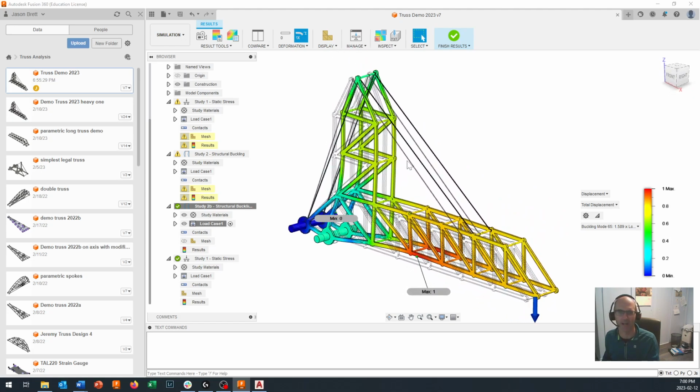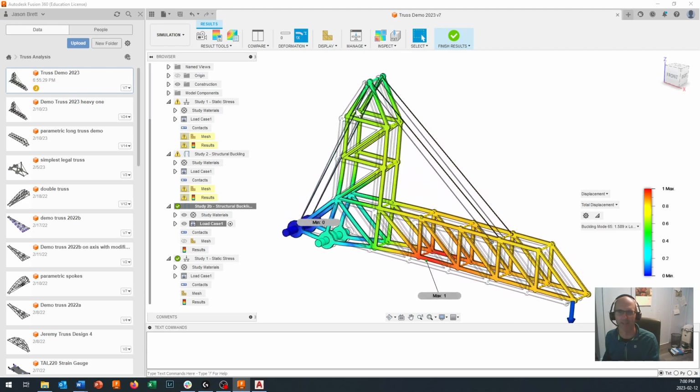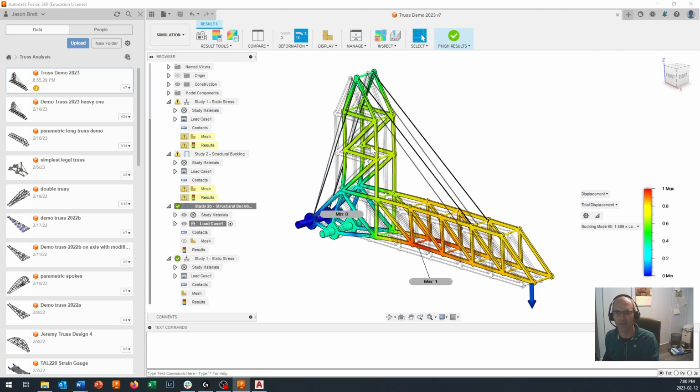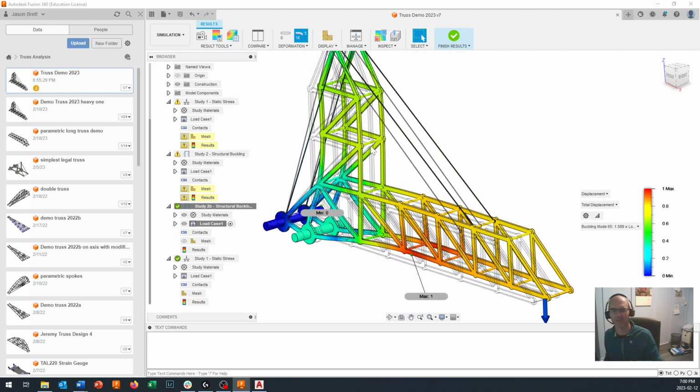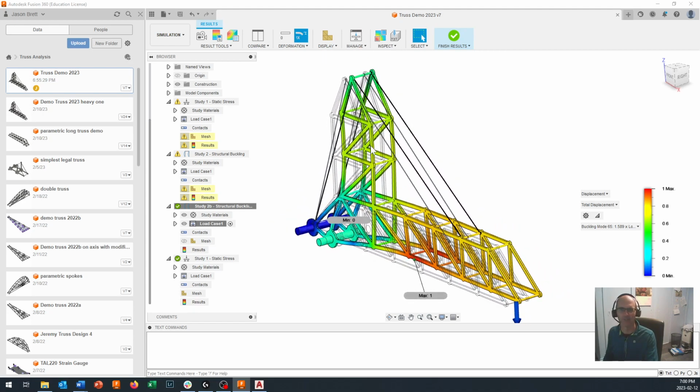I didn't get a good practical reading on that one because I built my truss wrong and had this string interact with that node right there. So I can't tell you how accurate that is or not, but based on what I've seen, that's probably pretty accurate, aside from the fact that I think my elastic modulus for the hardboard is a little bit high. And again, we can figure that out by taking some actual measurements in class. So there we go. You can start in AutoCAD.